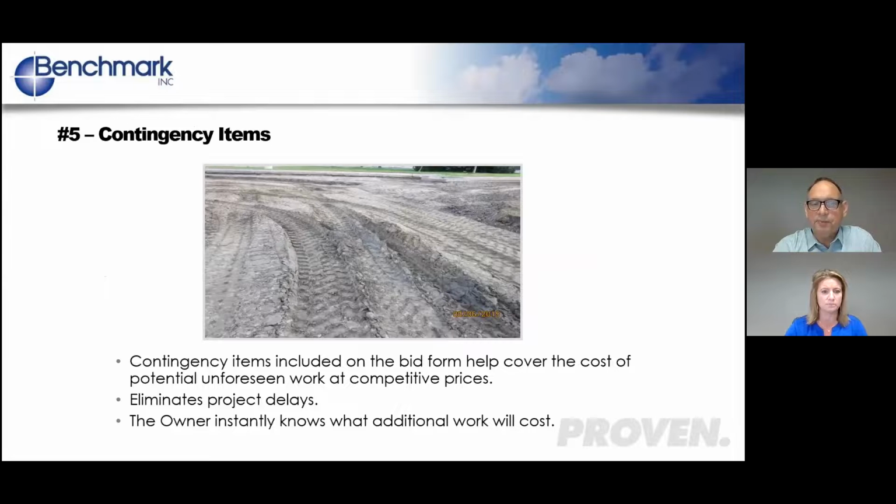Yeah, it's always best to get those prices for those contingency items when the contractor is trying to get the work. You're always going to get more competitive pricing for undercutting or base patching. So unit pricing is definitely the way to go.